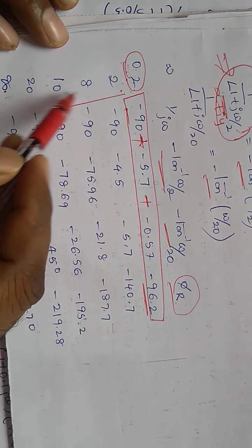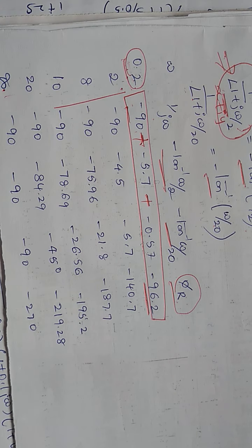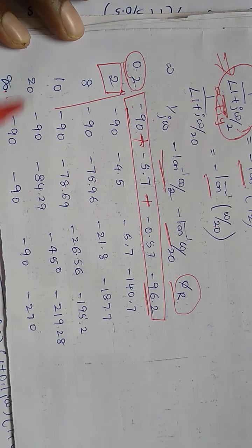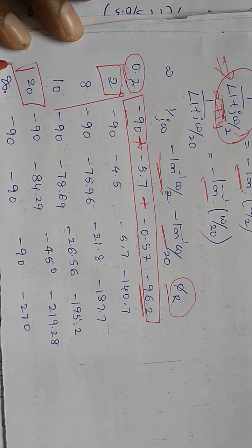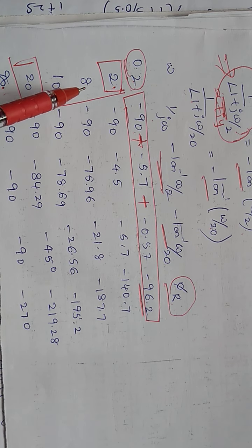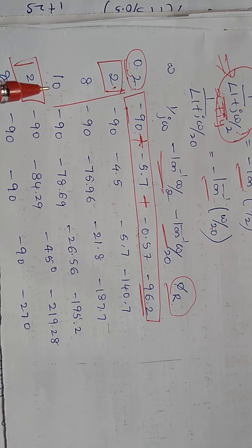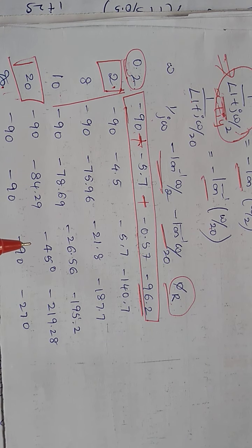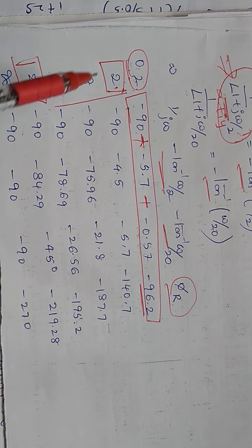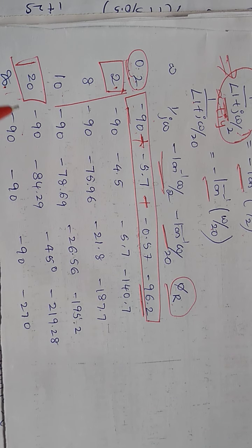In between these two values, you have to select a corner frequency. Our first corner frequency is 2 and the next corner frequency is 20. Between 2 and 20, we can select either 1 or 2 values, because we can identify where exactly the slope meets the magnitude plot, or in the phase angle plot, where exactly it meets the 180 degree line.